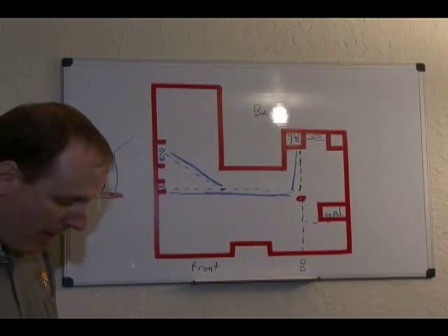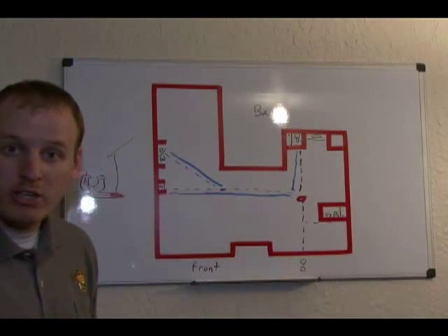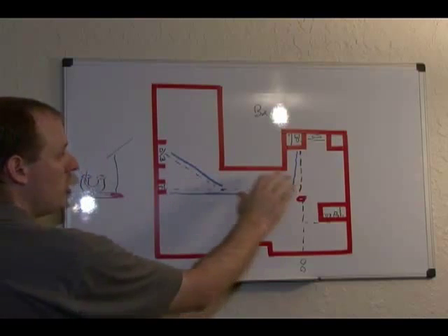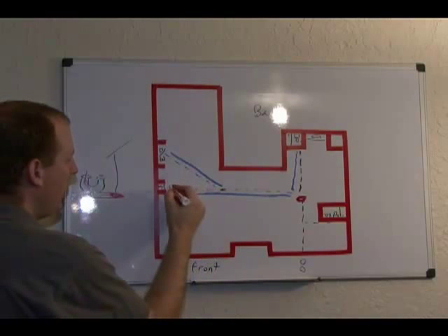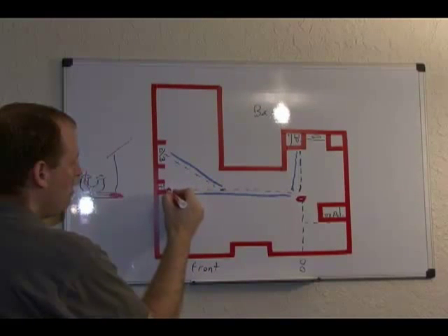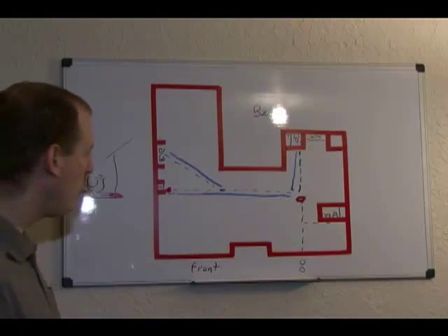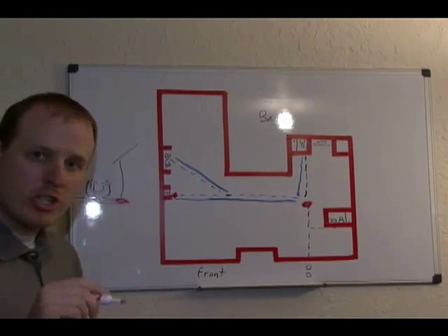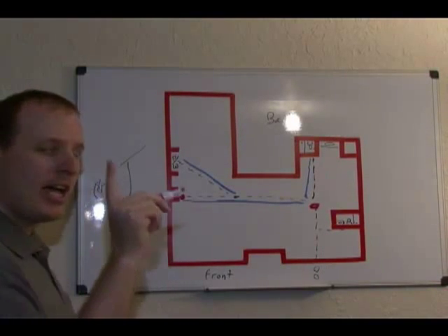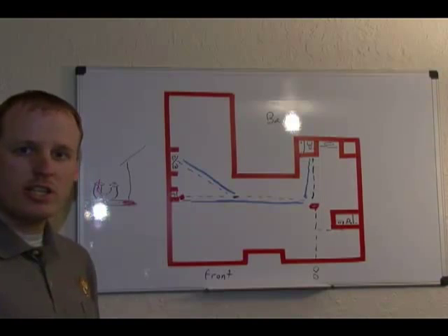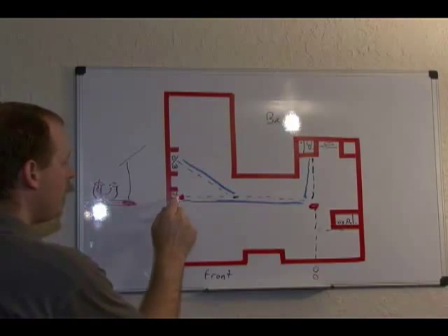Okay, now what we have to do is go track down where this leak is. We can leave this test ball in here, just like it is, so that we don't lose this water. We can then go and place another test ball right here, okay, which would be most likely what we would do. We could place a test ball at the washing machine as well, but likely we would place a test ball first at the kitchen sink in this illustration. We place that test ball at the kitchen sink, and because we said there was a leak at the kitchen sink earlier, there would then be a leak. And we would know that the leak is at the kitchen sink.